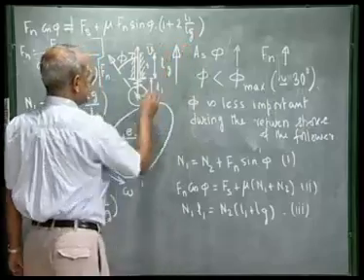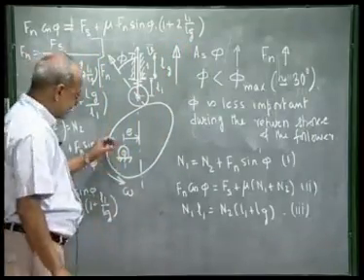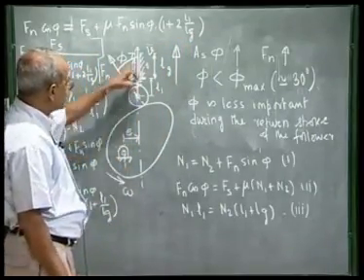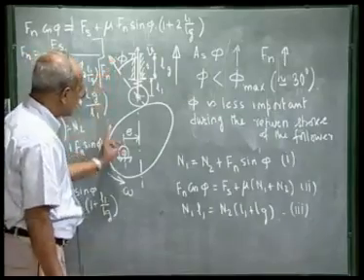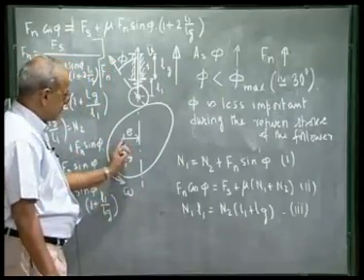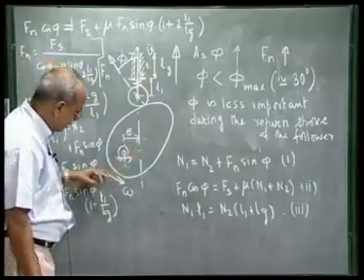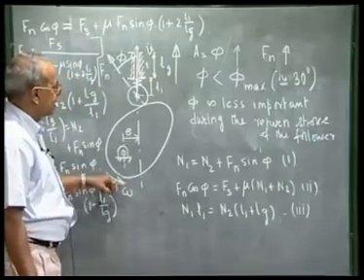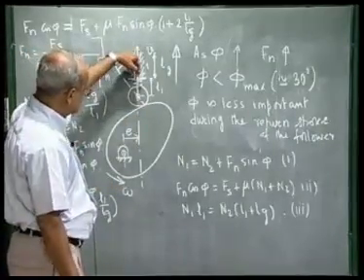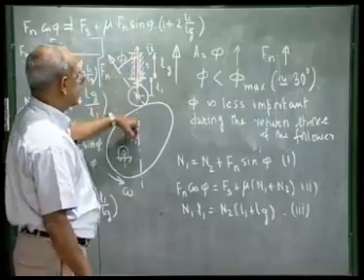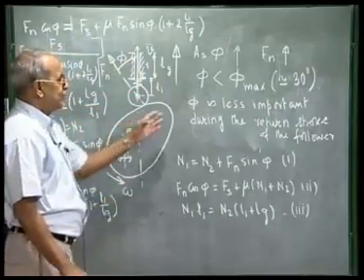During this movement, when the follower is being pushed by the cam, and that is when the driving effort is necessary, the maximum value of phi will be reduced by having this positive offset, that is to the right when the rotation is counterclockwise. And during the return, as I said, the spring pushes the follower down and the value of the pressure angle is less important.